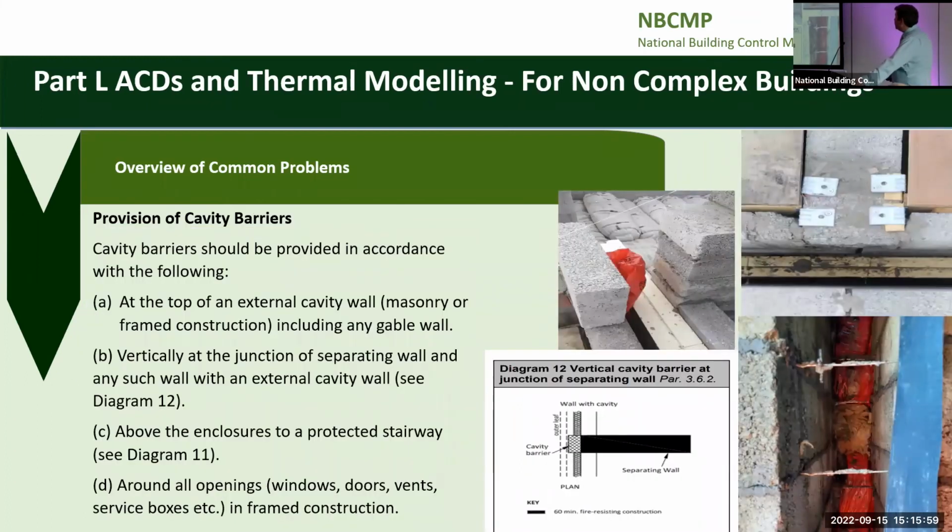Provision of cavity barriers. These are examples where they're missing completely. We'll say half put in right and half put in wrong, but still wrong. And blown-in cavity: you're putting in a bead, and if this was down in Cork or Kerry or Donegal, the moisture can get in here, that insulation is not going to fire, it's going to get wet and it's not going to be effective.